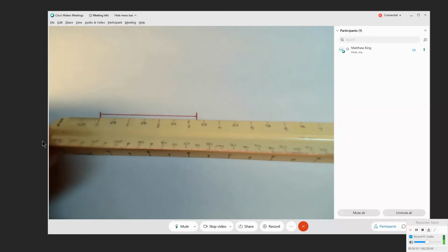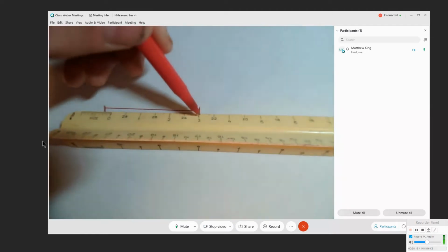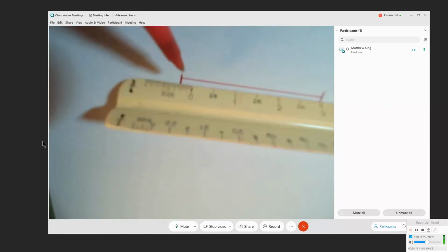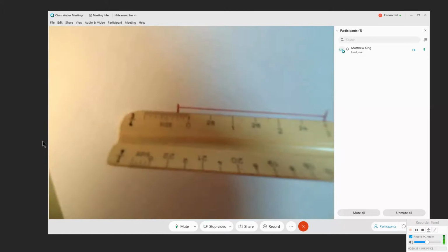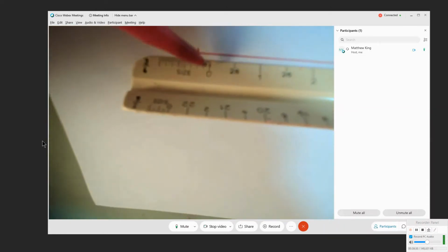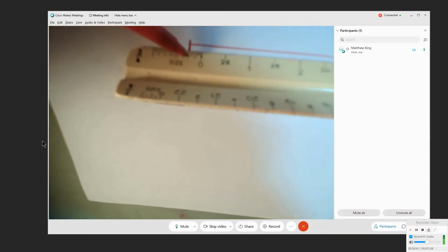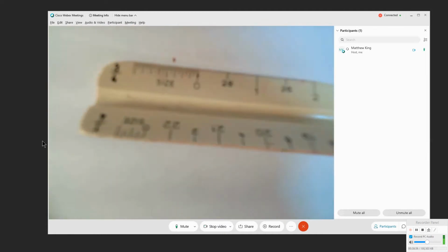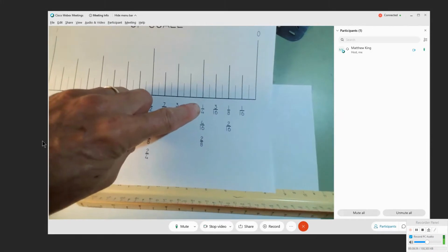So now what I do is I slide the scale down so that it's 3, and then I look over here to see what the larger part of 3 is, right? And this is where you really have to look carefully. And if I count increments, it's 1, 2, 3, 4 16ths, right? 4 of those notches. But I know I can't say 4 16ths. 4 16ths is a quarter.